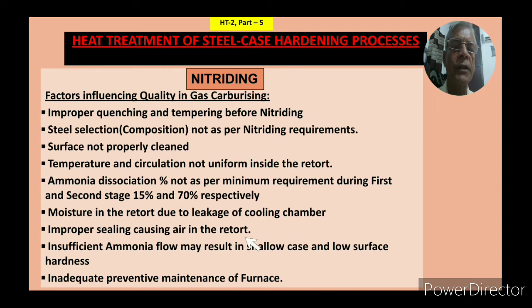Improper sealing causing air in the retort. This is also very important. If there is any leakage, then the air will come inside the retort and it will spoil your case because it will get oxidized. So nitriding will not be possible, or if it is possible, then you will not get better properties.